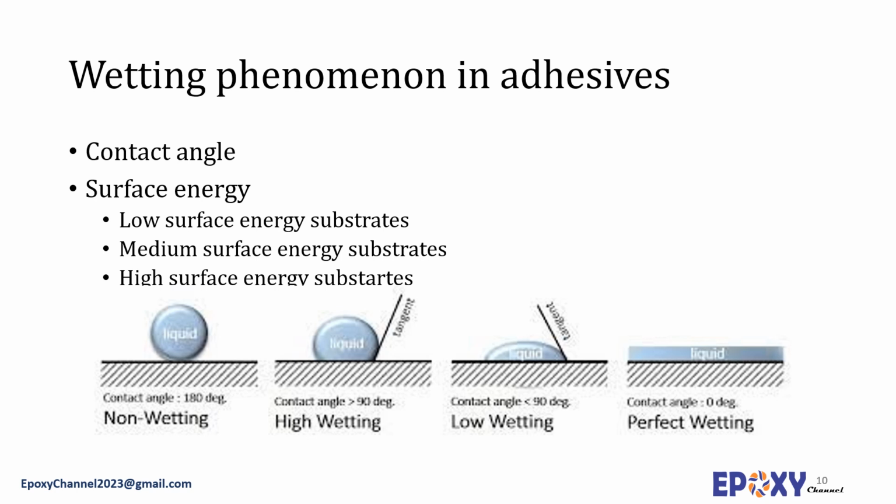This means that epoxy adhesives are not capable of wetting relatively low energy surfaces such as polyethylene, whereas the reverse is expected with high surface energy solids, for example metals. It should be mentioned that the absorption of atmospheric contaminants and moisture can reduce the surface energy of metals and is detrimental for the adhesion process. This also indicates the need for surface pretreatment before applying an adhesive.